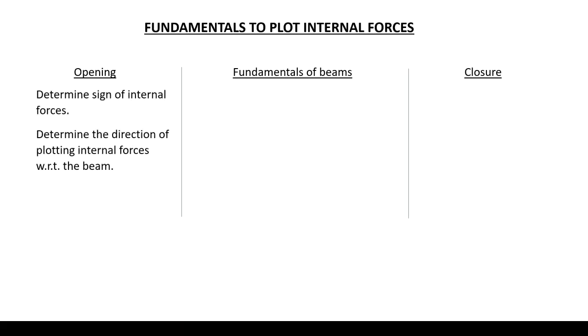We'll discuss fundamentals to plot internal forces. These are divided into three main parts. The opening: we determine the sign of internal forces, whether positive or negative. We determine the direction of plotting internal forces with respect to the beam, above or below the beam.